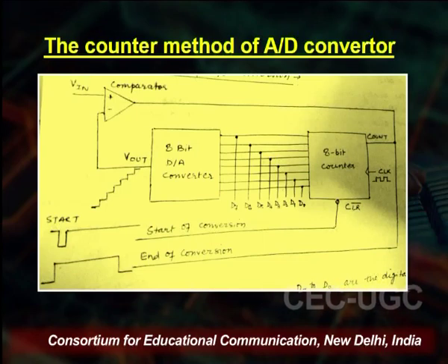In the circuit, you can also see that there is a counter. It goes in a U shape from left to right. You see the output of the op amp going into the counter, and then from the counter it is being fed into the 8-bit DA converter.